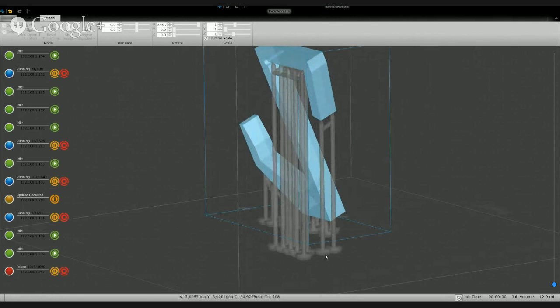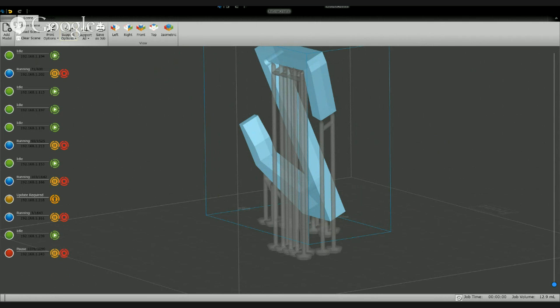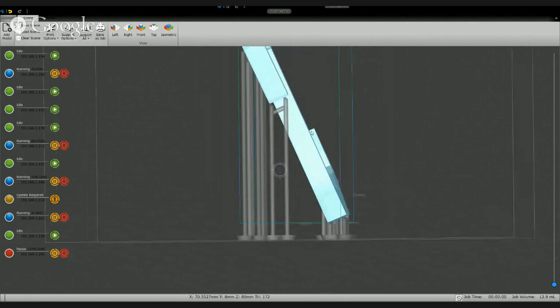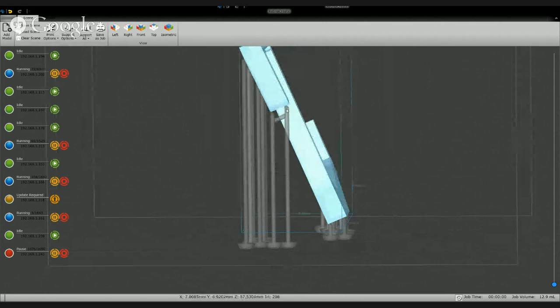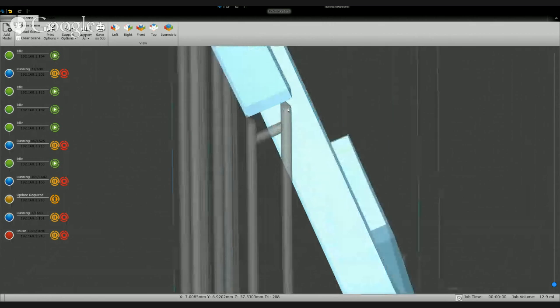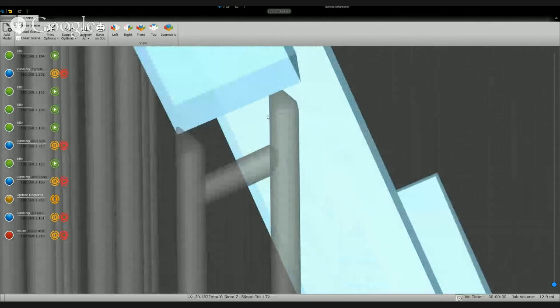The base height refers to the height of these little attachment points on the build plate, and it's in millimeters, so it's set to 2 millimeters right now. The cone length is at the tip of these supports. The cone starts around here and extends into the model, and so the cone is 2 millimeters long. Its height from this, let me zoom in, from here up to the invisible point inside the model is 2 millimeters.